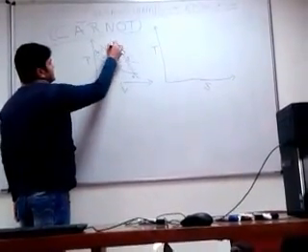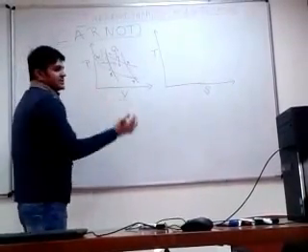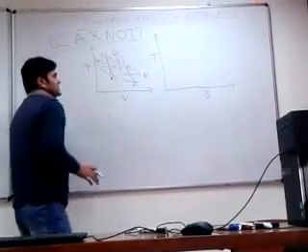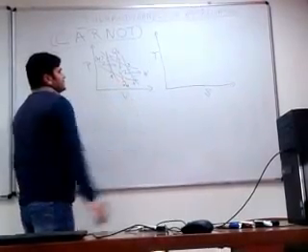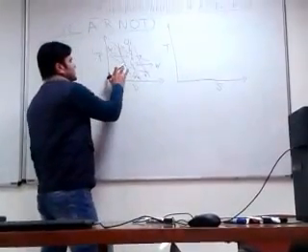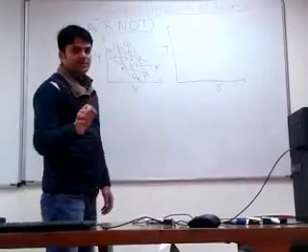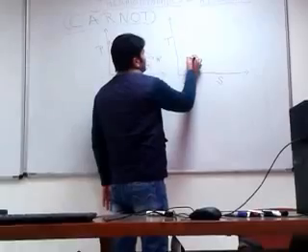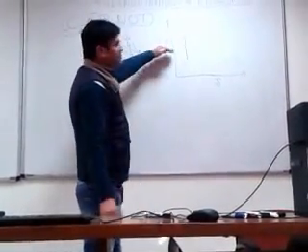From 3 to 4 there is an expansion, and in expansion work is given by the system. And from 4 to 1 there is heat rejection at constant temperature. Now drawing the same cycle on a TS diagram. Start from the compression adiabatic. As we know, the reversible adiabatic process is also called the isentropic process, and in an isentropic process the entropy remains constant. So it is a vertical line from 1 to 2.